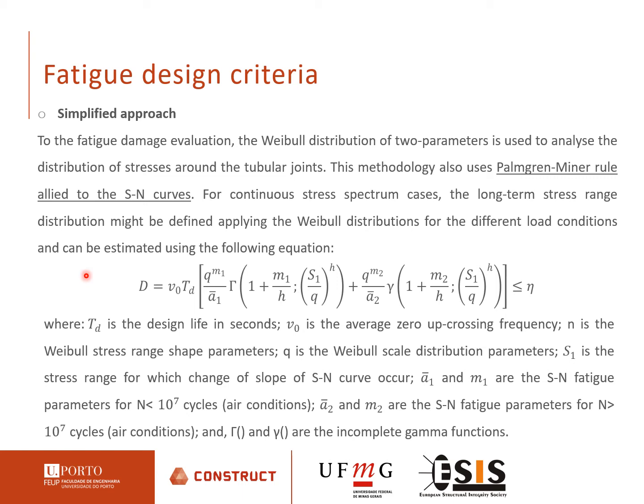For continuous stress spectrum cases, the long-term stress range distribution might be defined by applying the Weibull distributions for the different load conditions and can be estimated using the following equation. The variables annexed to this method are defined here.